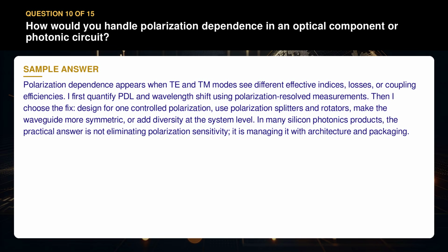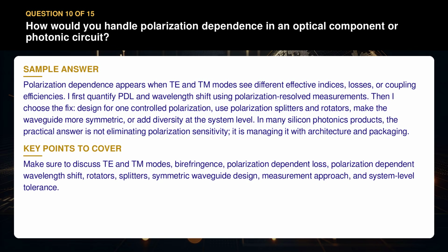In many silicon photonics products, the practical answer is not eliminating polarization sensitivity, it is managing it with architecture and packaging. Make sure to discuss TE and TM modes, birefringence, polarization-dependent loss, polarization-dependent wavelength shift, rotators, splitters, symmetric waveguide design, measurement approach, and system-level tolerance.